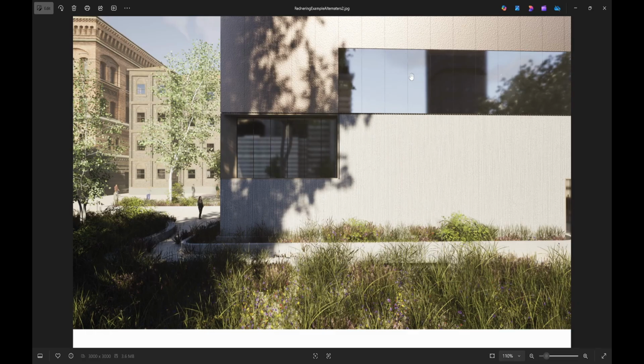I was saying maybe this is glazed glass versus frame glass pushed in. I would have added a space between the wood and the concrete here, just to reinforce that separation of materials a little bit more. I think it would have been helpful. All I had to do is use the Move Face command, move it down like an inch, to get that little dark gap. Like this is nice.